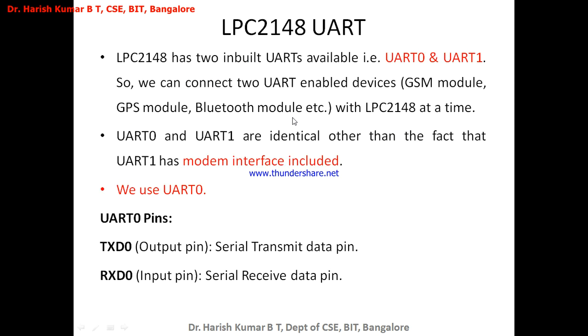Now you understood that LPC 2148 has 2 UARTs, UART 0 and UART 1, and they are identical, and the only additional feature found in UART 1 is that a modem interface is also included. But what we are using is UART 0, and it has 1 transmission pin and 1 receive pin.